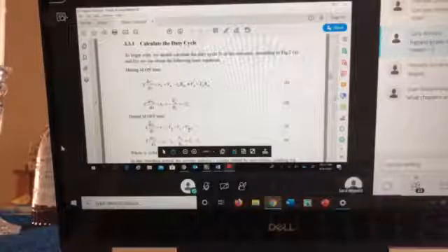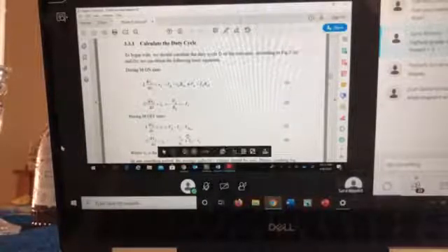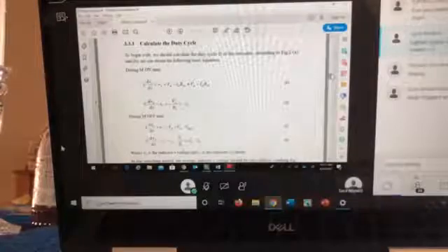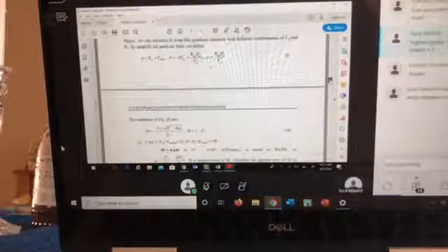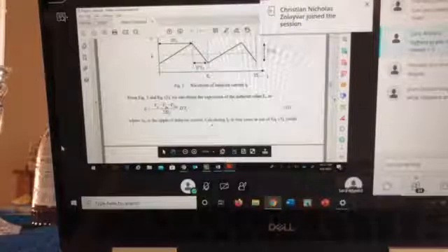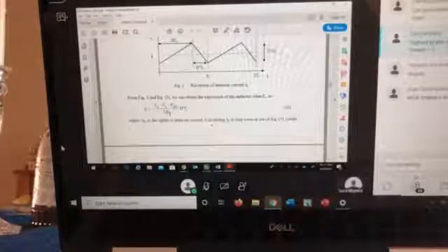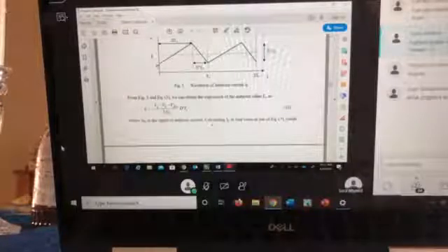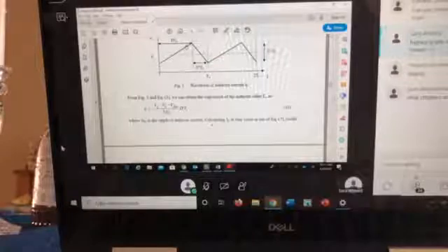So V of L is equal to VG minus V out minus VD on when the MOSFET is up. So I use this V of L, and here it is, and I divided it by L to give me my delta IL, which is the change in the current. So going back here, I have L is equal to V of L in that interval divided by 2 delta I L. Why 2 delta I L? Because the average value is here. We have one up, one down. But this V of L is the whole slope, right? So it's the whole line, which is 2 delta I L.